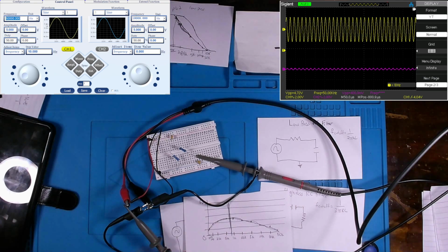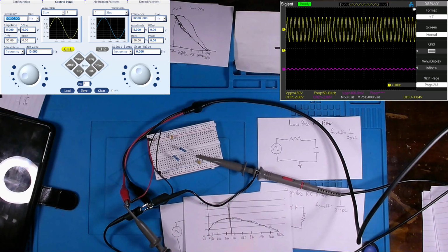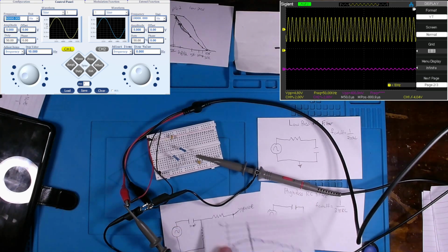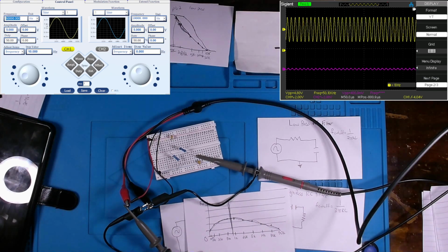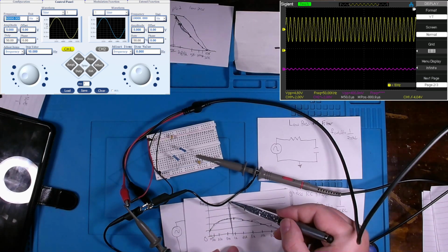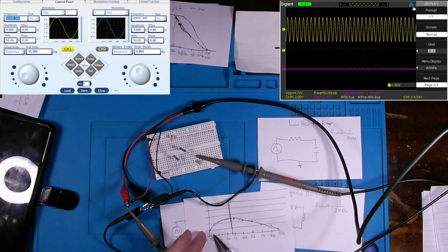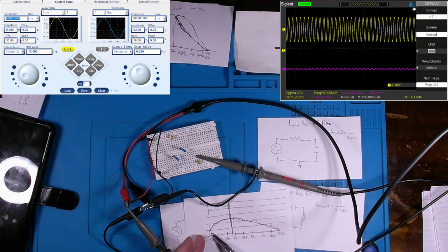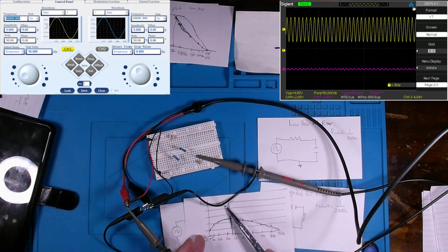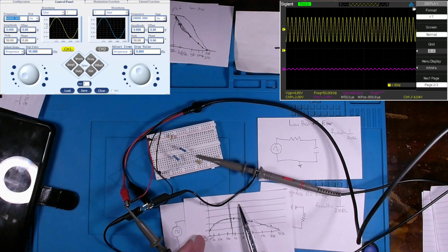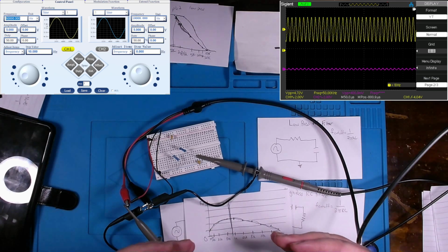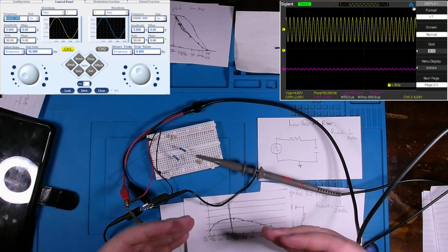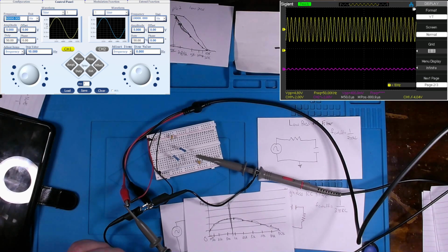And if you also notice, when we put these two RC filters in circuit with each other and establish one big circuit, it actually affects the entire amplitude of our circuit because we can no longer reach up to that 5-volt source that we are initially putting in, because both of these RC filters are having an effect one on another in attenuation.